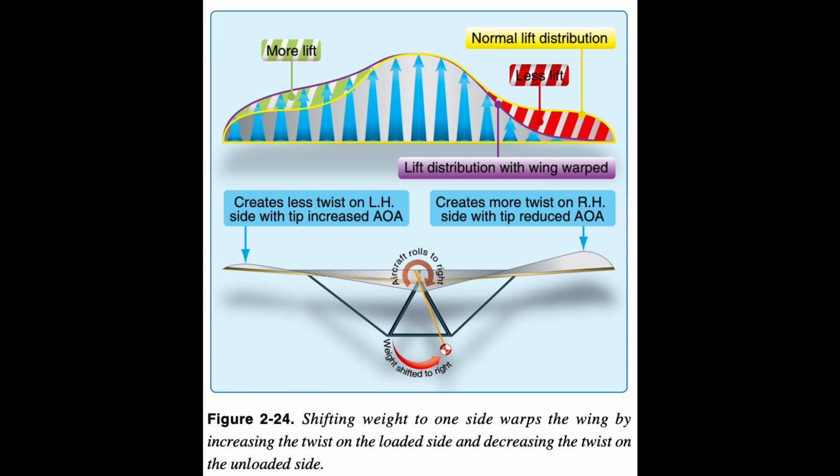The WSC wing is completely different and does not need a tail because of two specific design differences: a completely different airfoil design creating a more stable airfoil, and lifting surfaces fore and aft of the CG, similar to the airplane canard design.